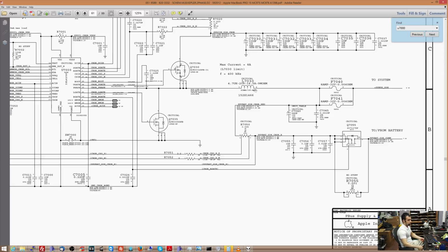And this is another thing that's important to understand here, is that you can tell when a circuit is working the way it's supposed to. Or for example, let's say that this thing is destroyed, right? You may get a different value when measuring the impedance of that circuit than you would if this was working. So understanding how resistance and how impedance measurements work, and also keeping a little Excel sheet for yourself of when a circuit is working, of what its impedance to ground is, of what the impedance is between different points in a circuit on a working board, can help you troubleshoot a bad board.